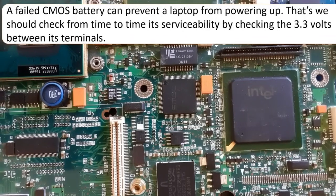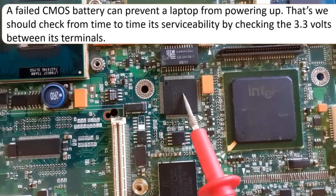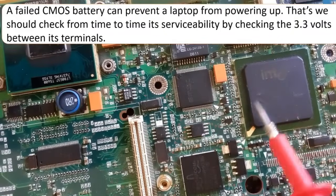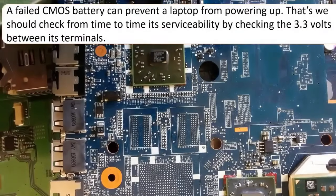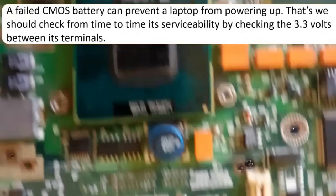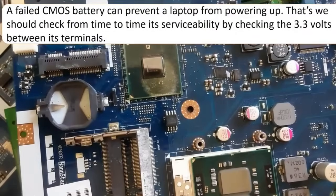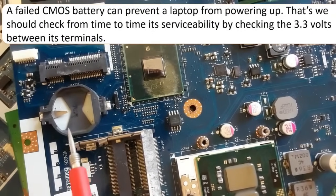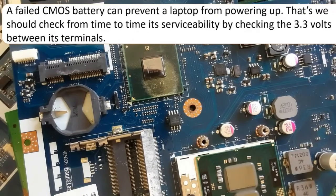As you can see, here we have the ICH. This is the BIOS, and this is the SIO. The four components are near to each other: the CMOS battery, the ICH, the BIOS, and the Super IO. So usually the four components are next to each other. Also for this motherboard, we have the CMOS battery slot, the ICH, the BIOS, and this is the Super IO.